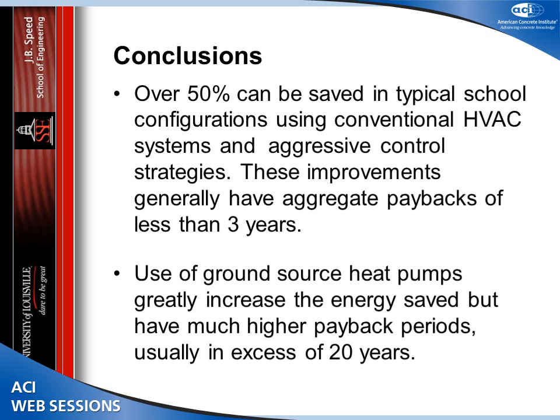All right, in conclusion, or in summary, we were able to save over 50% using typical school designs and conventional HVAC systems. All we changed is our control strategies. These improvements generally had paybacks well below 3 years. The use of ground source heat pumps greatly increased the energy saved, but our paybacks were generally above 20 years.